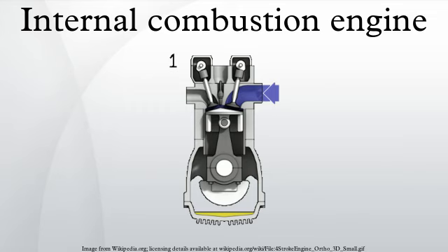Wankel. The Wankel engine does not have piston strokes. It operates with the same separation of phases as the four-stroke engine, with the phases taking place in separate locations in the engine. In thermodynamic terms it follows the Otto engine cycle, so may be thought of as a four-phase engine.